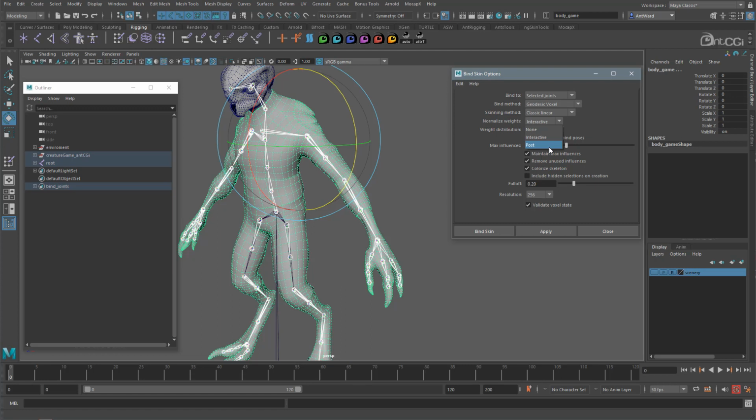Now, you can control how the normalization is distributed with this option. If you leave it set to distance, you will likely get issues with vertices being assigned the wrong weights. You may have seen this when you're smoothing weights and areas of the model seem to pop out. To combat this, simply change this to neighbour, so the weights, when normalized, are kept local. It will save you so many headaches and make painting weights a more stress-free experience.